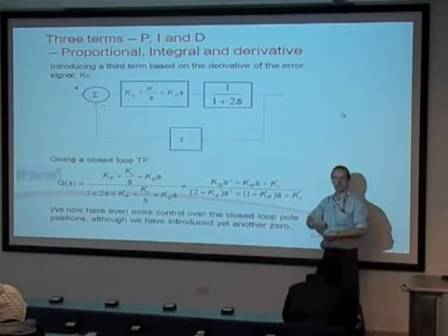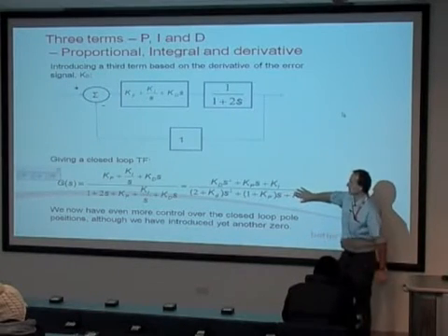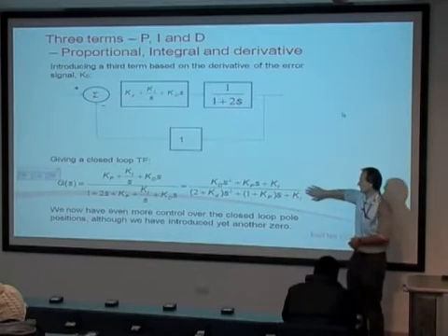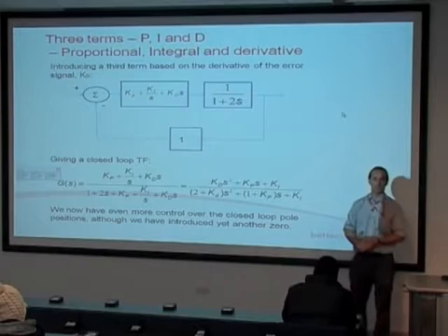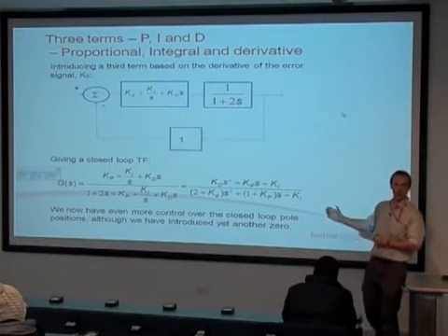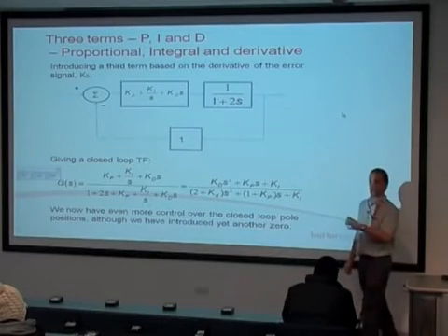Put them into the mix, three-term controller, off-the-shelf device, look at what happens to your transfer function when you blend it with your particular system, and you get something that looks like that. Okay. Again, you'll notice I'm glossing over my issue of having some zeros in the way, and the reason I'm doing that is because I've got a fix.